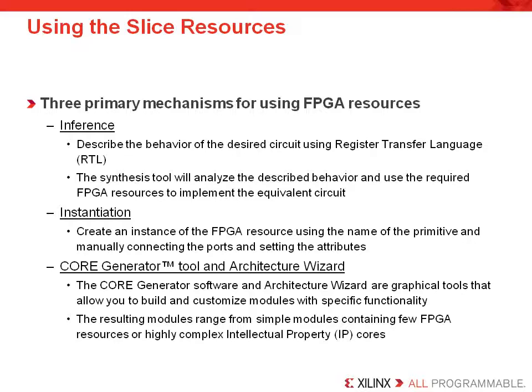All of the high-end synthesis tools have schematic viewers. The viewers are used to graphically display a gate-level version of your netlist and also a technology view of your netlist. While a gate-level netlist is worthwhile to check the Boolean optimization produced by your synthesis tool, the technology view helps you understand what Xilinx primitives were inferred by your synthesis tool or what primitives were not inferred by your synthesis tool.